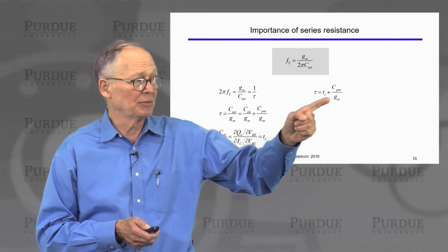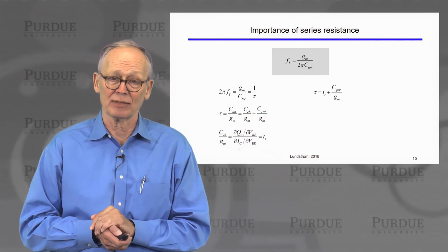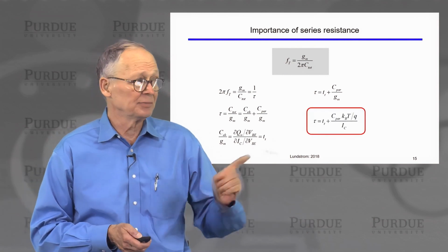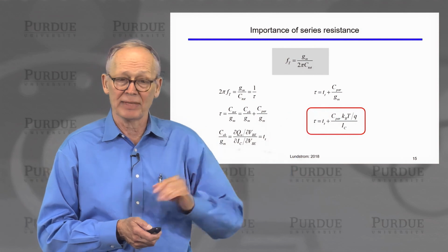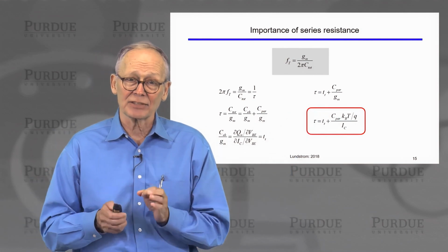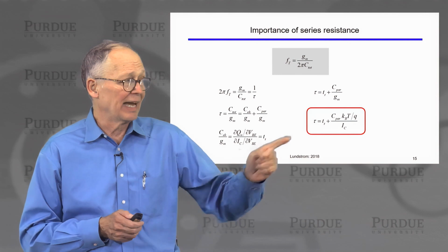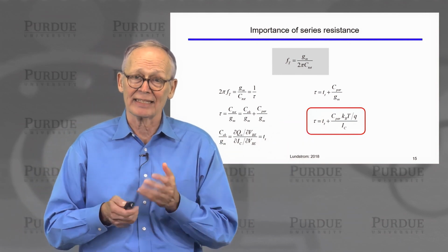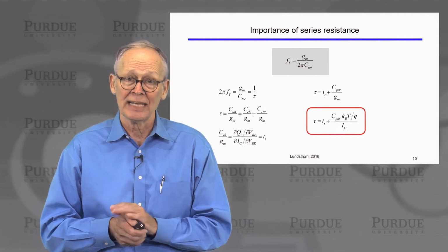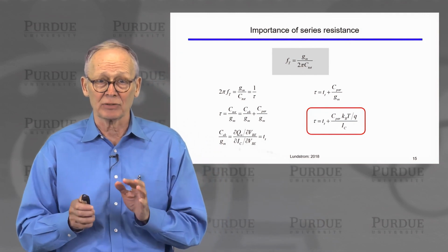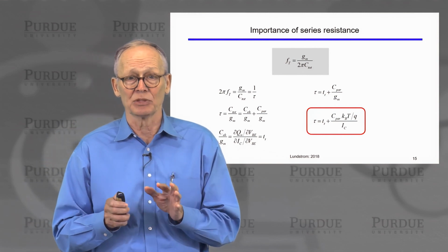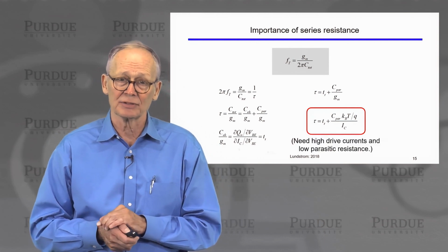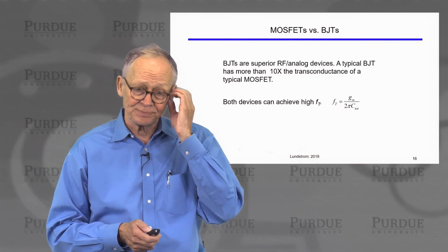Now, there is also a gm, AC parasitic over gm. That's going to give additional delay. But gm is collector current divided by kT over q. If I make the collector current large enough, I can make this extra component due to the parasitic capacitance small, and I can get high speed by making that negligible. That is the reason that for high frequency operation, we run bipolar transistors at very high current densities to try to reduce the effect of those parasitic capacitances.